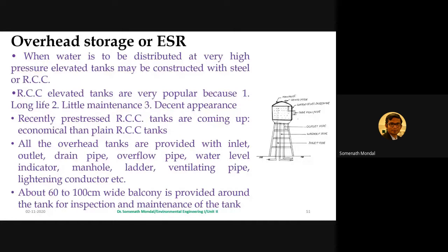Now, but in recent days, we have pre-stressed RCC. You know very well that the same concept has come in case of all those piers and flyovers, bridges. So we don't directly use RCC. Instead, we use pre-stressed RCC. And similarly, in case of tanks, also we can use pre-stressed RCC material, and they are even more economical than plain RCC tanks.